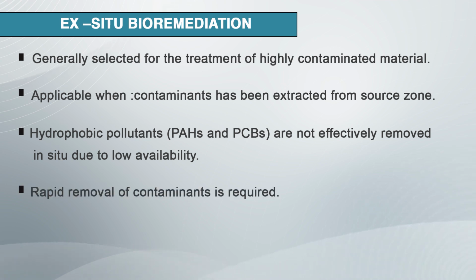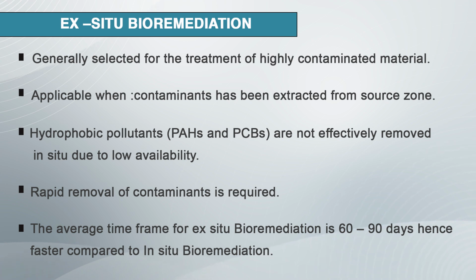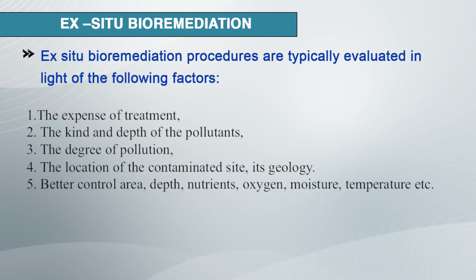It is used when rapid removal of contaminants is required. The average time for ex situ bioremediation is about 60 to 90 days, hence faster compared to in situ bioremediation. It is also better controlled in terms of area, depth, nutrition, oxygen, moisture, temperature, etc.